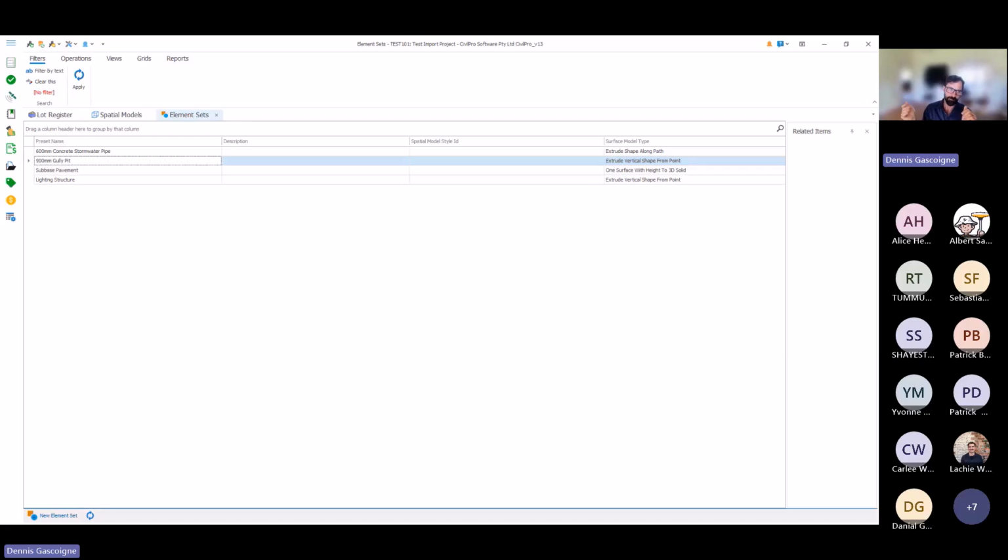That'll become apparent why. So what we do is allow you to reference one or more of these elements from a model, and then when we build our procedural model, we just go in and we look at that original IFC, find its components by UID. We append all of our metadata to do with the compliance to it, and we incorporate it in the new model. So you end up with this 3D model that comes with several different ways of procedurally generating.